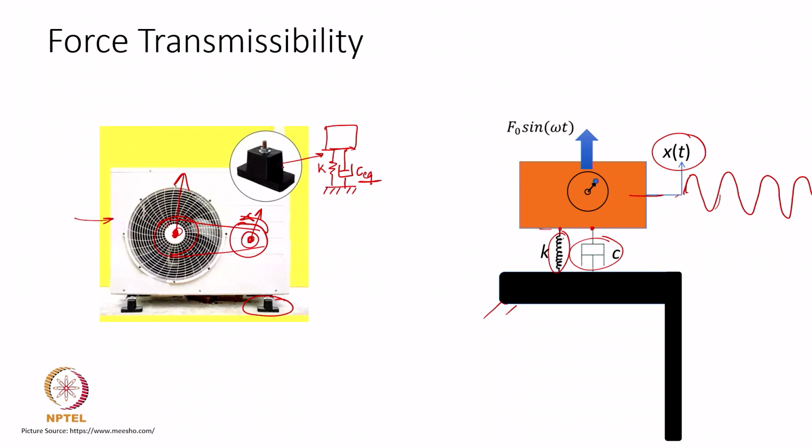Although there is no formal dashpot here, we have seen how this type of structural damping is modeled like a spring with a complex stiffness, that we already know. But for the sake of simplification, just treat this as a spring-dashpot system. Whenever there is a motion of the mass, there would be a stretch in the spring and a dissipating force generated in the dashpot.